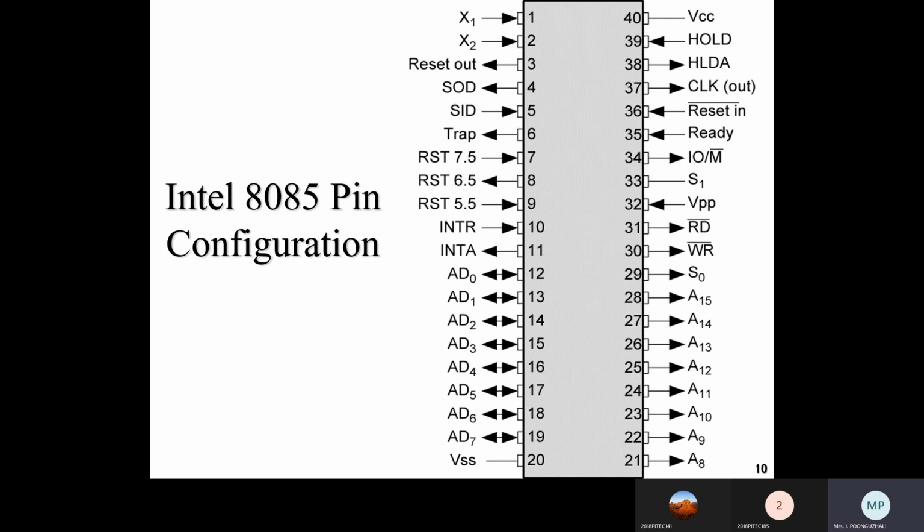So if you use separate address lines and data lines, the number of pins will increase. So to reduce that, address and data are multiplexed together. Depending upon the control line ALE, if ALE, address latch enable line, is 1, these lines act as address lines. If that control signal is 0, these lines act as data lines. Right, so 16 lines are gone for address and data.